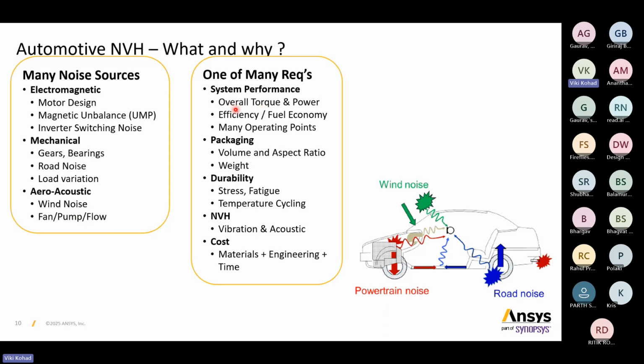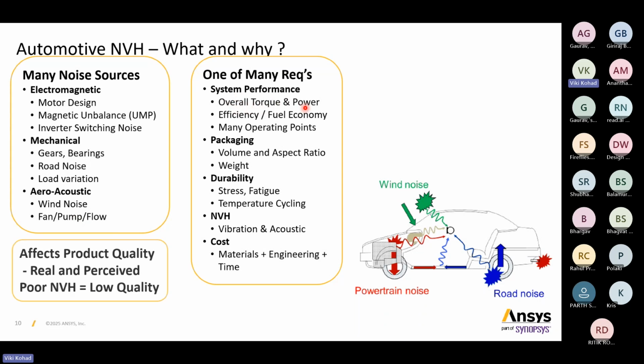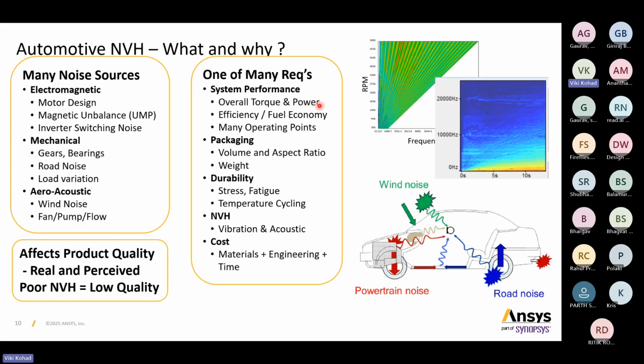One of the many requirements is system performance. We have to simulate the overall torque and power, then the efficiency and fuel economy at various operating points. It is not enough to simulate only one condition. You have to check the same motor under different parameters to see whether it works in different applications. Then there are packaging, durability, NVH, vibration and acoustics, and next is cost.